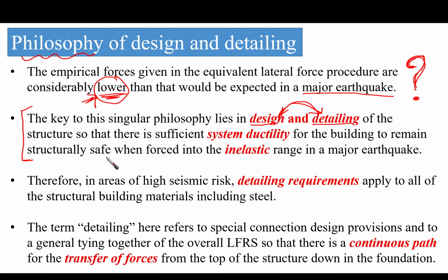Design and detailing of the structure so that there is sufficient system ductility. This is very important, as I explained in the previous videos. Do you remember the previous videos where I was talking about ductility issues and its explanation? So detailing and design are directly related to ductility. For the building to remain structurally safe when forced into the inelastic range in a major earthquake, whenever we have lower forces and proper detailing, our structure is going to be forced into the inelastic range, and there is some nonlinear performance of the structure.